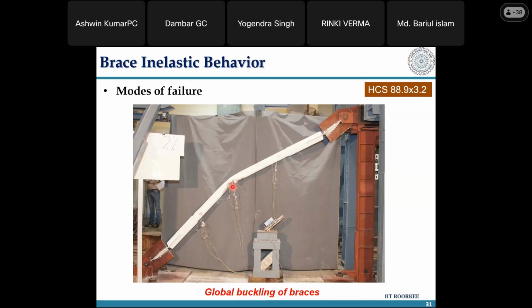But you understand that there is an n square also coming there, n square pi square EI by L square, which normally n becomes 1 as the first mode is what is governing the buckling. It's the least energy mode, so that has to happen first, and so we normally give n equal to 1. But if I give a strong casing around it, normally a concrete casing is given, you can give an all steel one also.